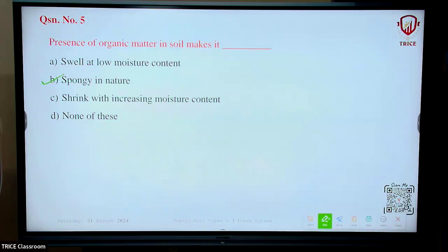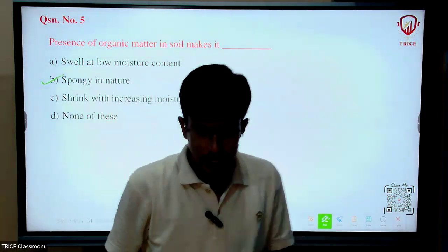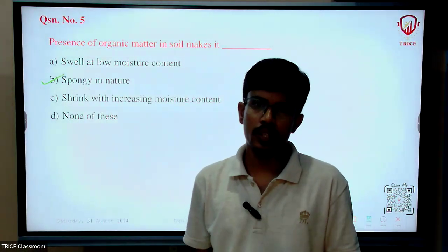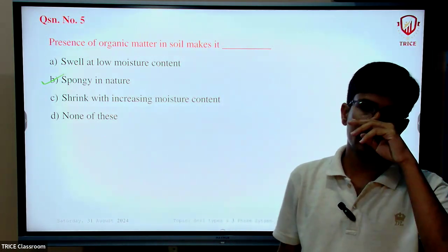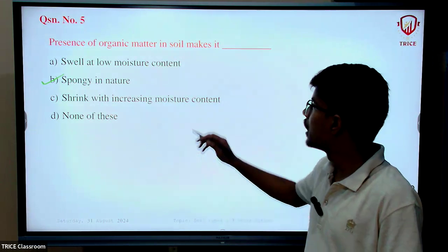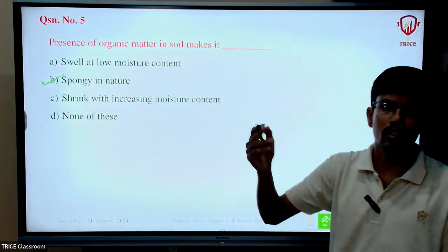So when we have swelling at low moisture content, it is the clay-forming minerals in black cotton soils, where we have montmorillonite clay or smectite or illite clay-forming minerals, that swell at low moisture content. This is completely inorganic soil, not organic.